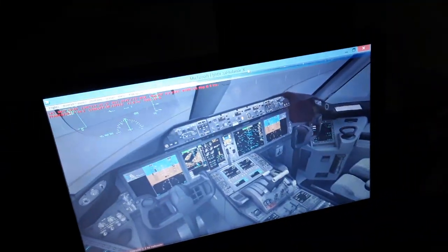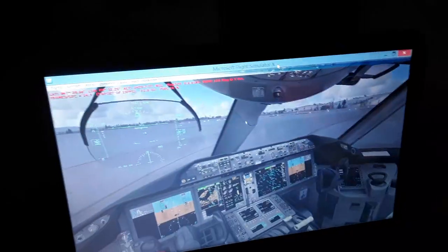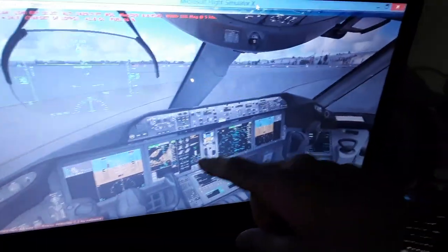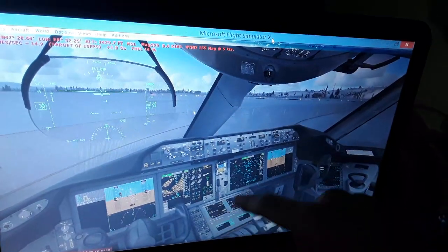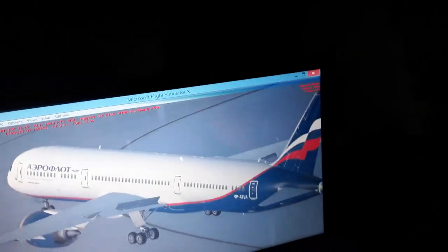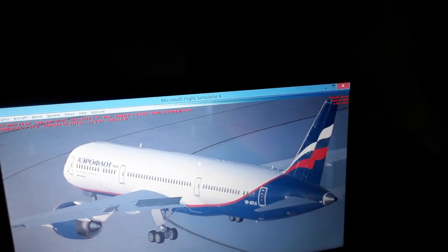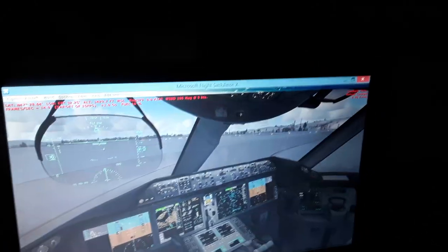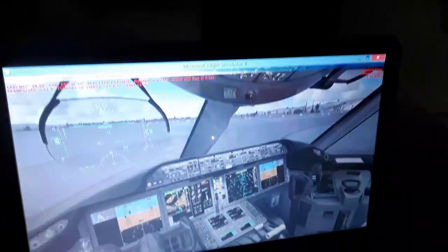We have also the navigation aids, the navaids, which are the VOR stations, ADFs and NDBs, and the waypoints. The waypoints are horizontal and vertical navigation fixes with altitude and airspeed constraints. You're going to see later through the flight management computer here, I will input all the data of this aircraft for this flight. So it's going to follow one waypoint after another, the route we're going to create for flying the Boeing 787-900.